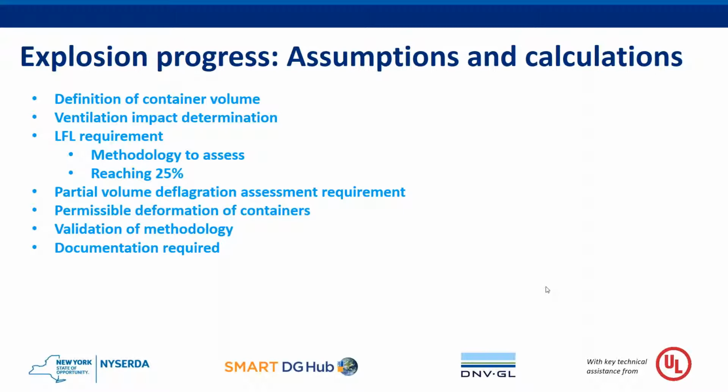However, it's recognized that NFPA 68 does give a good baseline, and that there are similar methodologies that can also be acceptable if they are demonstrated to be equal or more granular and specific than the methodology outlined in NFPA 68. NFPA 68, however, is the preferred methodology, and in all cases, it's required that when executing methodology, you provide essentially your work. You need to show your assumptions and how you selected and validated the model or analysis methodology which was chosen.